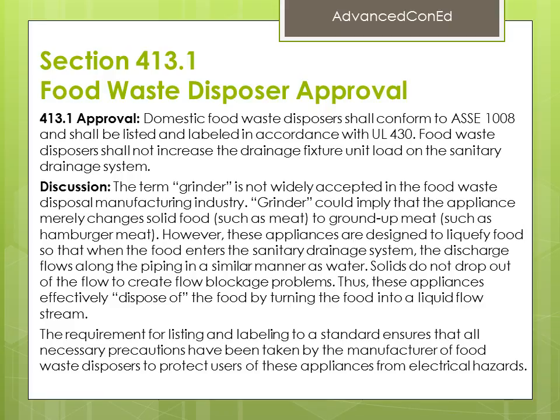Discussion. The term grinder is not widely accepted in the food waste disposal and manufacturing industry. Grinder could imply the appliance merely changes solid food, such as meat, to ground up meat, such as hamburger meat. However, these appliances are designed to liquefy food so that when the food enters the sanitary drainage system, the discharge flows along the piping in a similar manner as water. Solids do not drop out of the flow to create flow blockage problems. Thus, these appliances effectively dispose of the food by turning the food into a liquid flow stream. The requirement for listing and labeling to a standard ensures that all necessary precautions have been taken by the manufacturer of the food waste disposers to protect users of these appliances from electrical hazards.